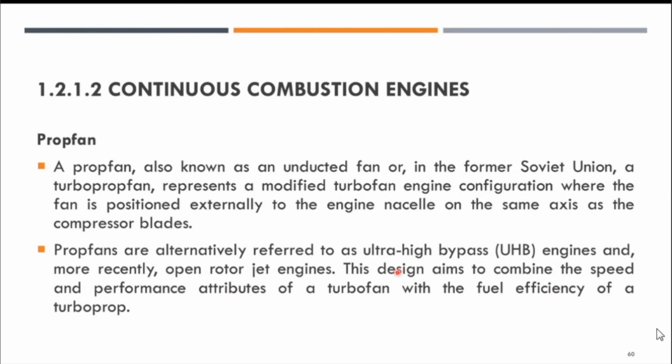Next, we look at the prop fan. What is a prop fan? It is also known as an unducted fan, because the fan is outside the engine. You will be interested to see the picture of the prop fan. In the former Soviet Union, a turboprop fan represented a modified turbofan configuration where the fan is positioned externally to the engine nozzle, compared to internally. Okay, it sits on the same axis as the compressor blade. A prop fan is alternatively referred to as an ultra bypass engine.